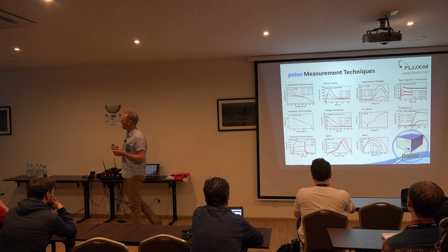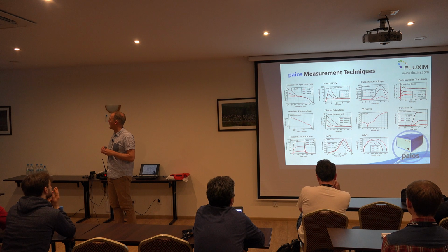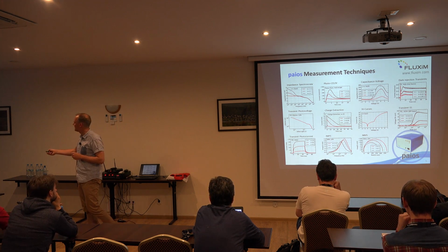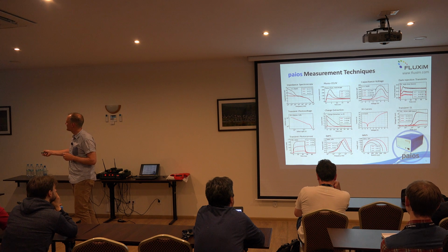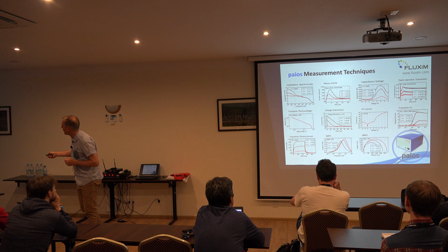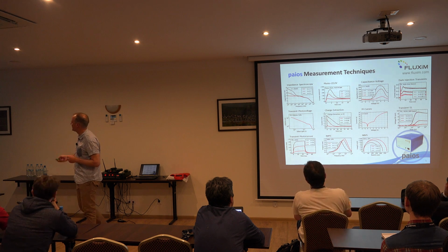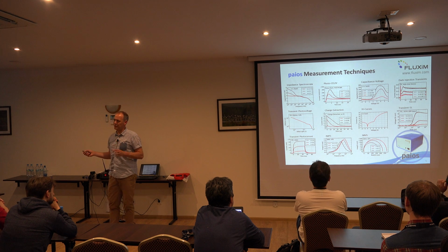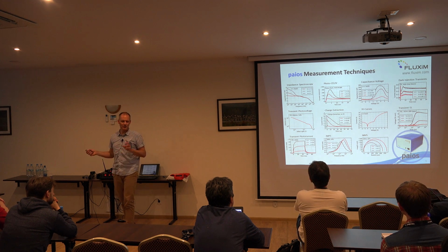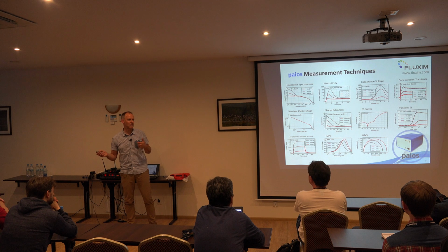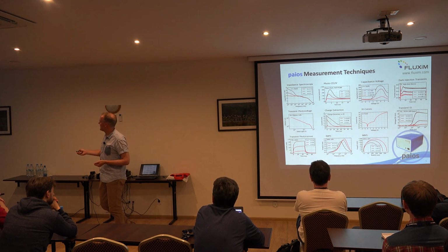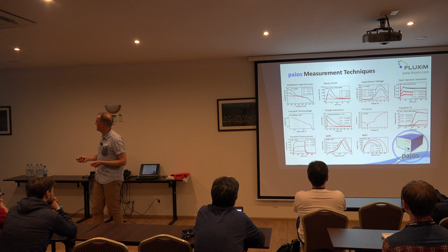So this gives you an overview of typical measurement techniques. On the upper left, we see an impedance spectroscopy measurement where we sweep the frequency of the applied AC voltage, and we plot, for instance, the capacitance versus frequency. Then photo-CELIV is known from solar cells, but I will show a modification of this technique for OLED characterization. Then we have capacitance-voltage, which I mentioned in the modeling talk already.